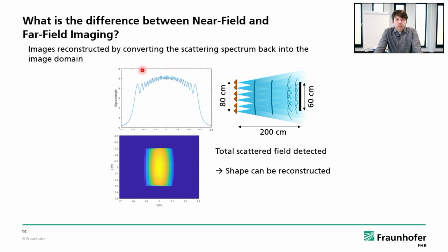So if we reconstruct the entire image from these antenna signals, you see the bar completely reconstructed. The distance is reconstructed by the delay, and the angle is reconstructed from our spatial Fourier transform. So you can completely reconstruct the object.